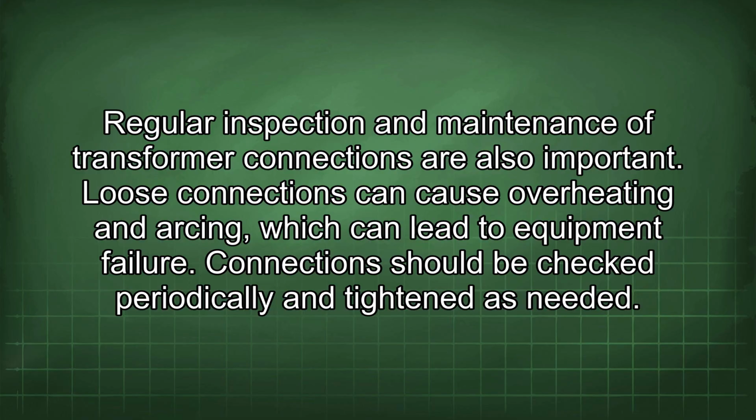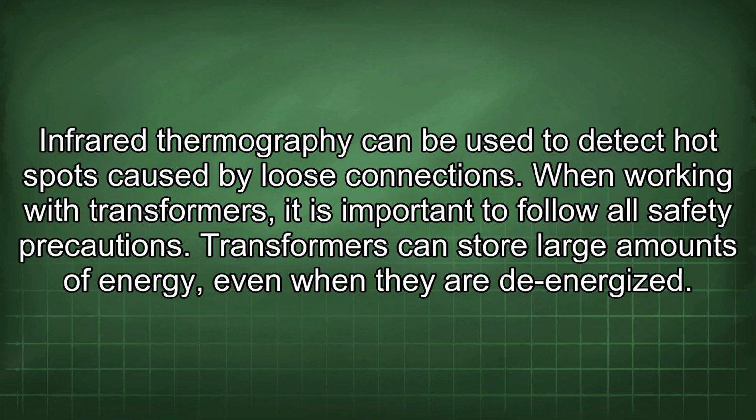Loose connections can cause overheating and arcing, which can lead to equipment failure. Connections should be checked periodically and tightened as needed. Infrared thermography can be used to detect hotspots caused by loose connections.